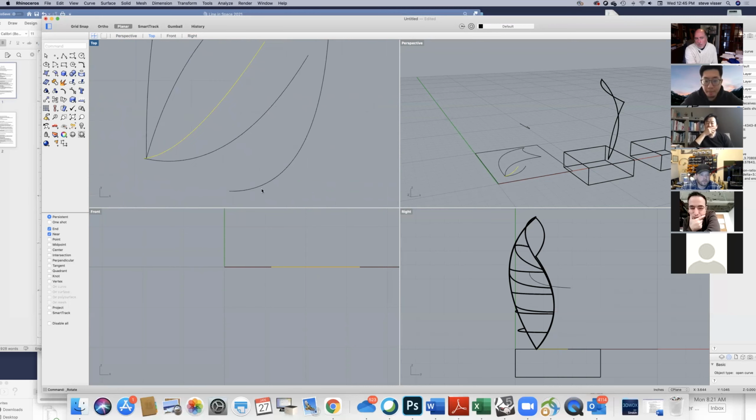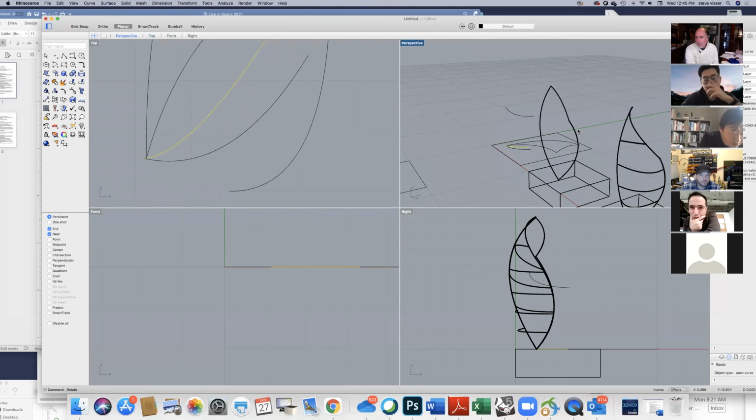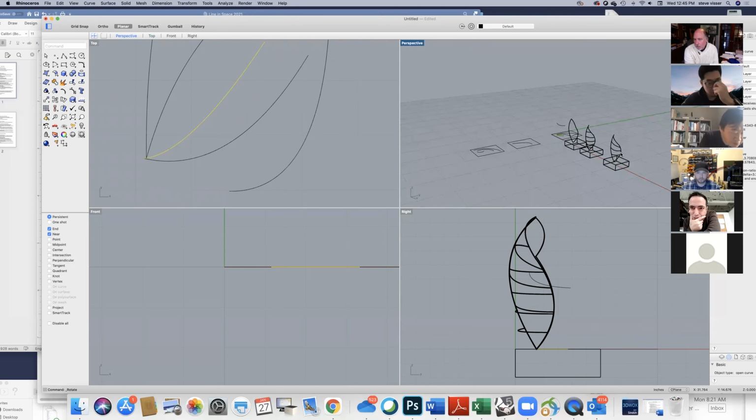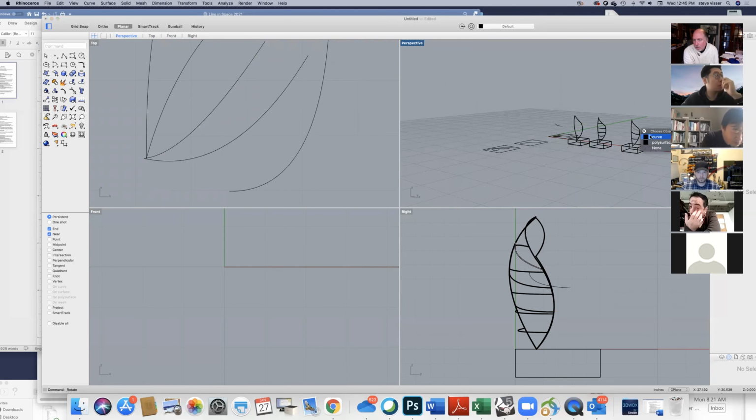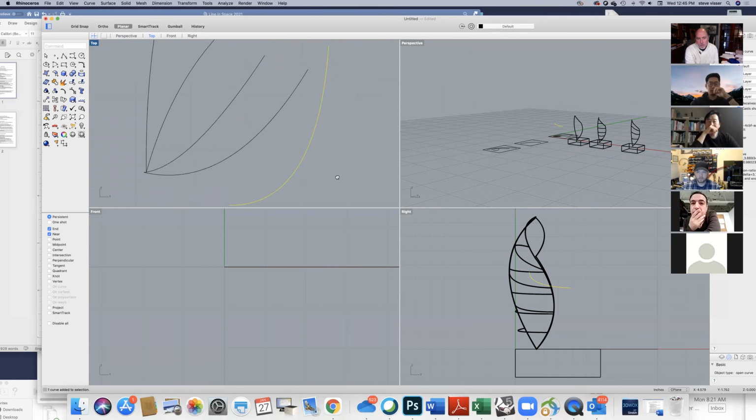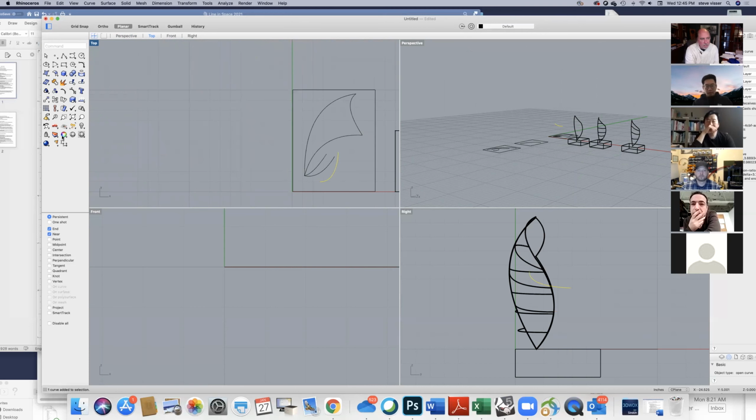All right. Now, one thing that the student does need to sort of keep track of is which of these arcs is which within here, and where it is along that arc. So for example, the one that we're doing right now, this arc up here is this arc I've copied here. So just to keep track of it, they may want to actually move it to its location. So instead of going to the corner, they may want to go endpoint and say, this is the one that goes up top here.